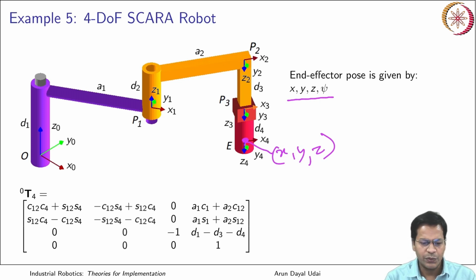And total orientation, you know, it is the sum of all the angles that your robot has rotated. Your end effector has rotated along the vertical axis only, because this is a robot which doesn't have any roll and pitch angle. It can only rotate about the vertical axis. So it makes things quite simple.